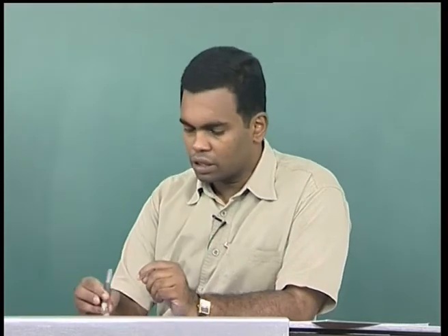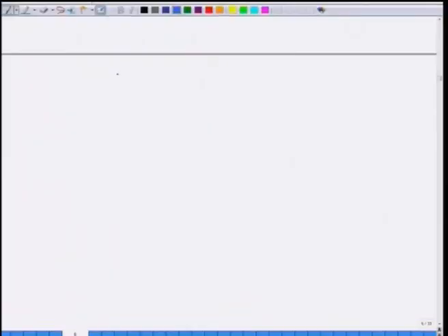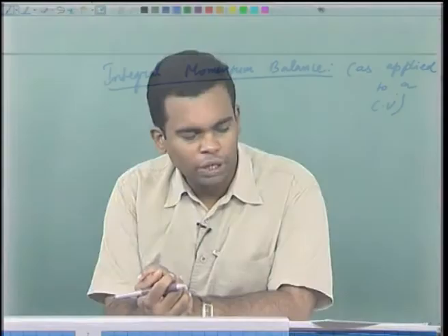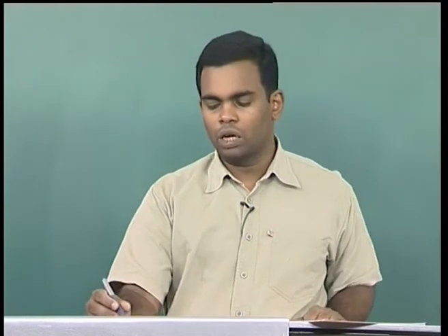The next topic in integral balances is the integral momentum balance, as applied to a CV. We want to derive an integral balance for momentum as applied to a control volume, but we have to go back to the control mass approach, because really speaking the momentum balance rests on Newton's second law of motion,